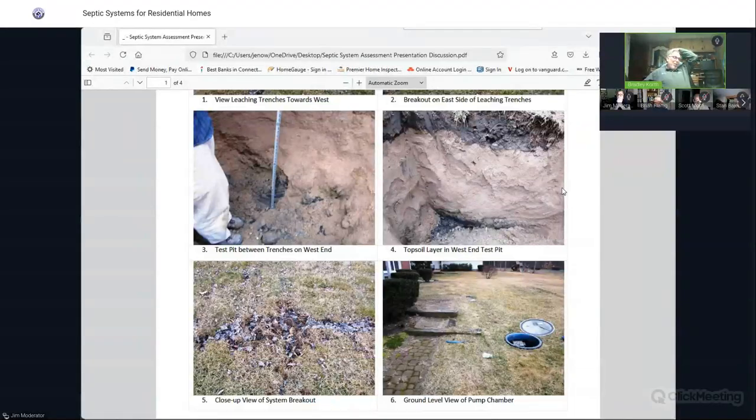And they say, "Yeah, how'd you know?" What's happening is groundwater in Connecticut can go up and down several feet between the high and the low, and the high part is typically February through April or May, depending on how much rain you get. That was actually the case in this one too. It worked good most of the year when the groundwater was lower, but it didn't work very well when the groundwater was higher.